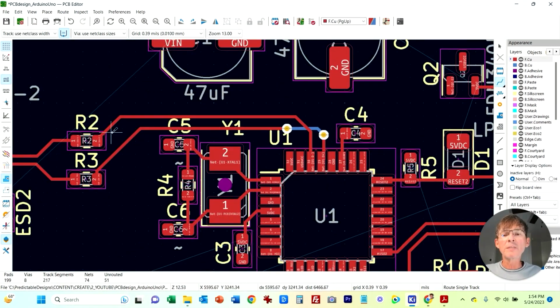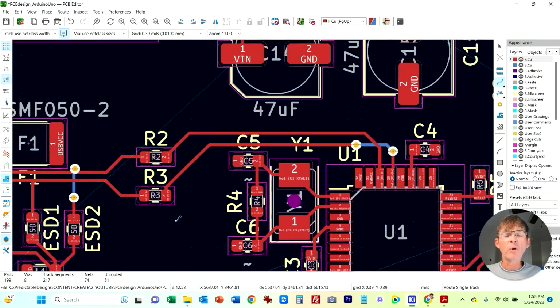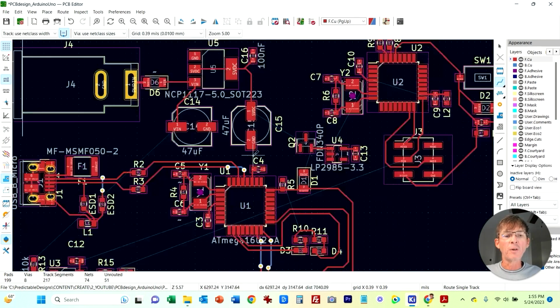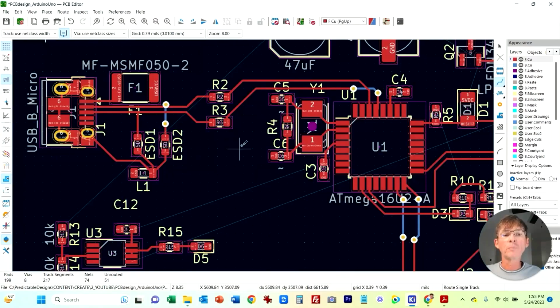And normally, like I said, you want the USB lines to be the same. This one is a bit different because it does have a via that goes down to the bottom layer just to cross over it there. But I'm not going to worry about it. I don't think it's really going to make that much of a difference. They're still pretty similar. The main thing is you just would not want one of these routed all along the outside of the board and having one really short.